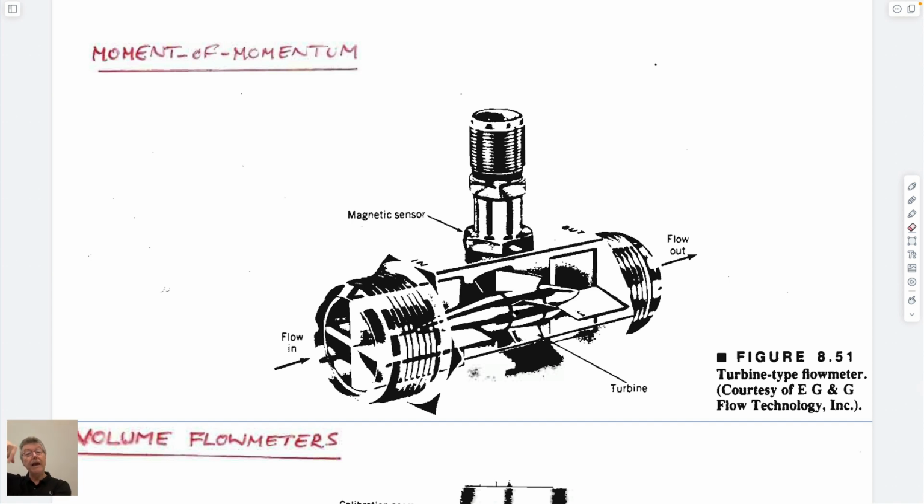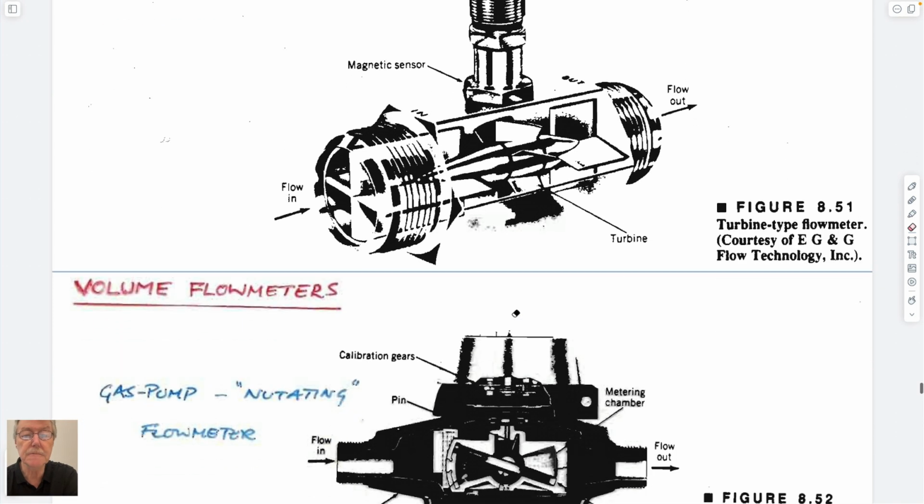It has a small impeller on it, and the impeller gets turned as it goes through stagnant fluid and then is brought up through the same stagnant fluid. If the fluid is flowing, then you get a different velocity profile of the impeller on the way down than you do on the way up. And so you can tell from that if some water is going into the formation or coming out of the formation in the hole. So it's exactly the same as this.